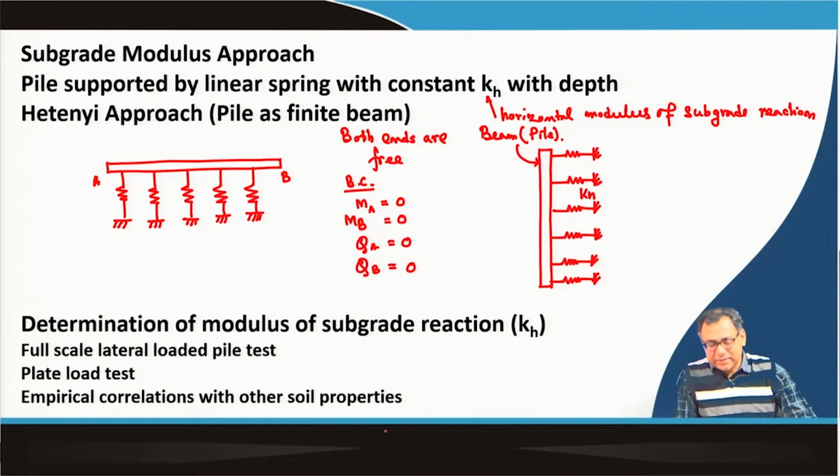Then, as these boundary conditions have to be satisfied for the finite beam, we apply end conditioning forces M0 and P0 at A or B, so that the net bending moment and shear force will be zero at end A and end B.